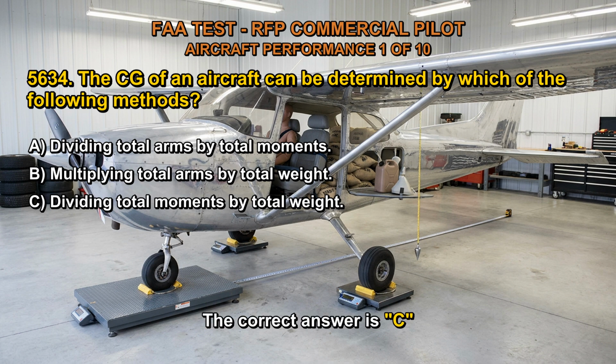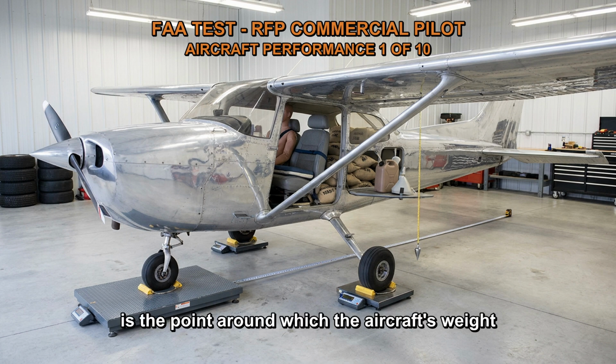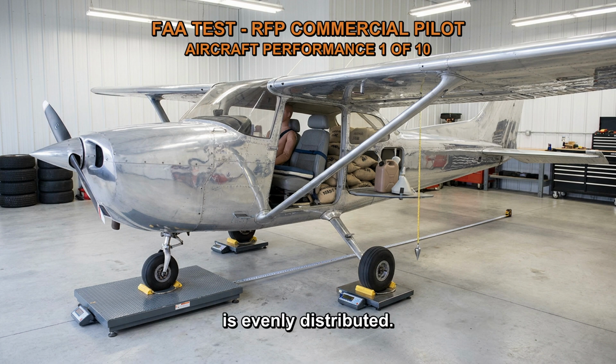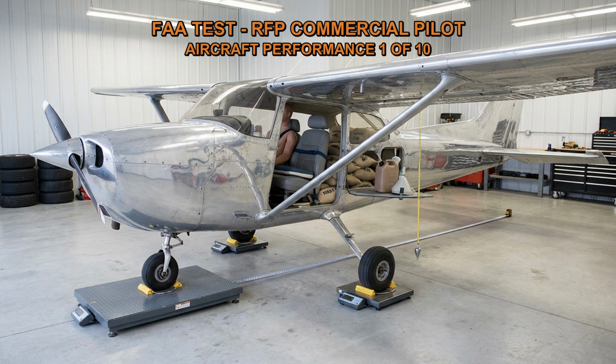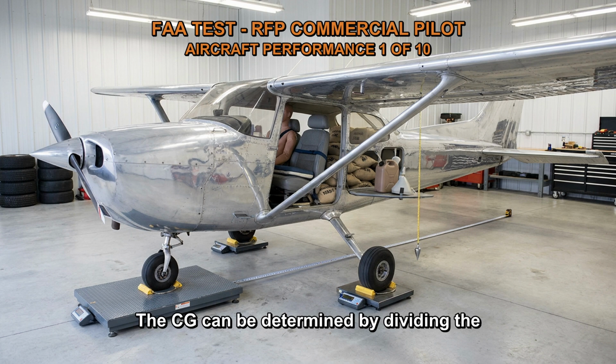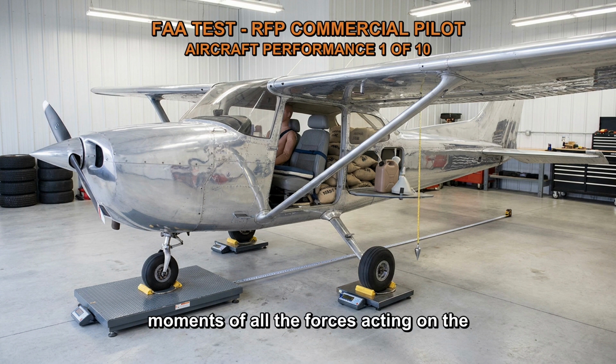The correct answer is C. The center of gravity, CG, of an aircraft is the point around which the aircraft's weight is evenly distributed. It is important to know the CG of an aircraft because it affects the aircraft's stability and handling characteristics. The CG can be determined by dividing the total moments by the total weight. The total moments are the sum of the moments of all the forces acting on the aircraft.